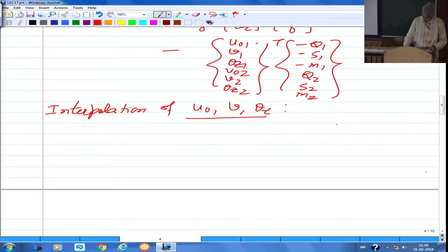So that is what at the beginning I also talked about, the degrees of freedom, and based on this we said that we must assume at least a linear polynomial for u, for v as well as for theta z, and therefore we ended up expressing the unknown constants in terms of the values of the variables at node points. So this was N1 into u naught 1 plus N2 into u naught 2.